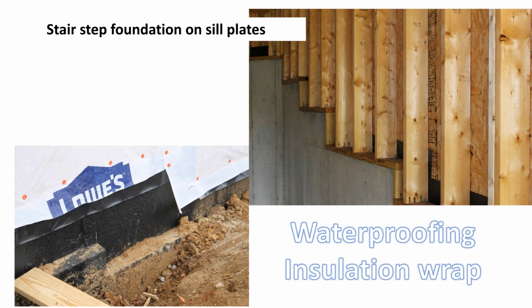and the moisture doesn't get in there next to that sill plate. This is a 2x6 exterior wall. That's a good thing. 2x6 is obviously going to be a little bit more supportive than a 2x4. So they oftentimes will use a 2x6 on an exterior wall.